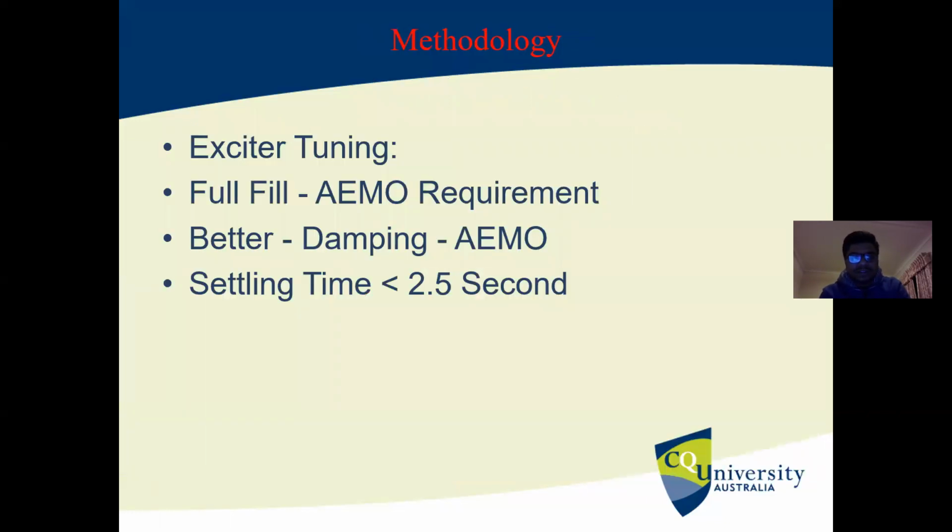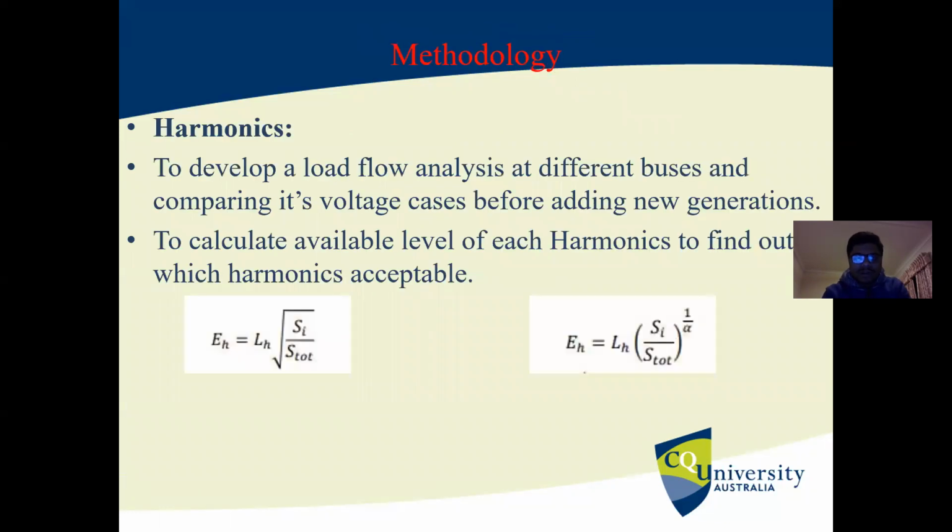And the last one is exciter tuning. By using the settling time of 2.3 seconds, we get better damping and fulfill the minimum requirement of the Australian Energy Market Operator. And now I would like to invite Vivek Akannapalli and hand over to him for the harmonics.